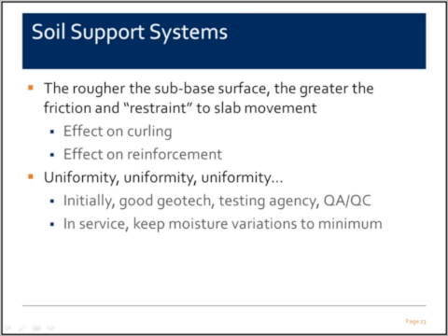There are other issues involved with concrete shrinkage and soil supports. The rougher the subbase surface, the greater the friction and the restraint to the slab movement, which are the ones that add to the cracking potential of the concrete. That restraint has an effect on curling, and it does have an effect on the amount of reinforcement that you want to put in.